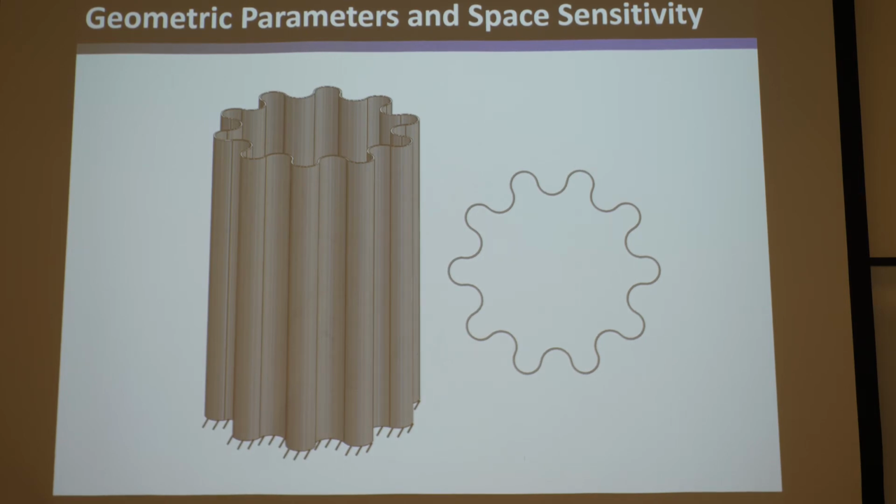But the third definition is just comparing directions of stiffness quantitatively. But of course, that's very difficult to do because there's four different kinds of stiffnesses. There's force to displacement, there's force to angle, and then there's torque to angle, and then torque to displacement. And those are the four different kinds of stiffnesses you can get, and they all have different units, right? And so, you know, it's difficult to even compare them because you're comparing apples with oranges.